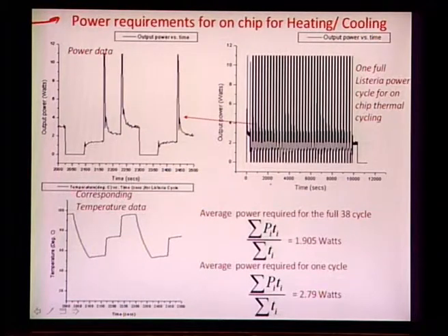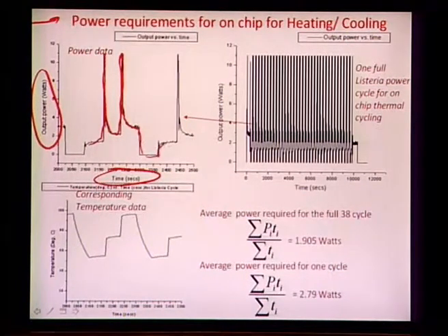What you do is you acquire the voltage and current values over a substantial amount of time, and then you calculate the output power by multiplying that. So, this is essentially how a power profile would look like. Powers as you may see here are getting higher as there is a temperature ramp up requirement, and it falls down as there is a sudden switching off of the heater because of ramping down, and so this is the applied power essentially.